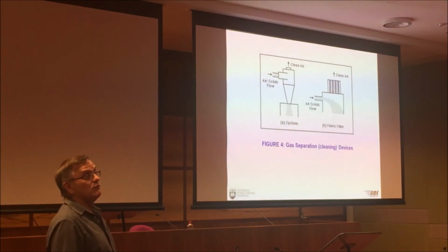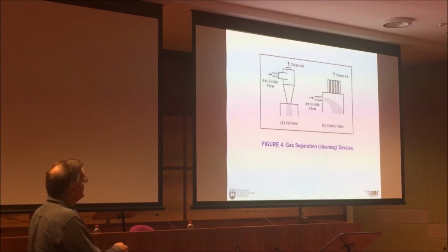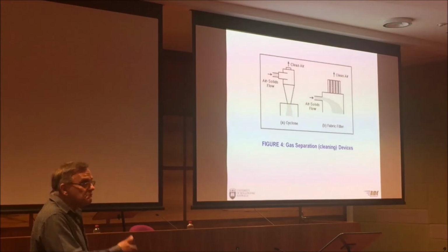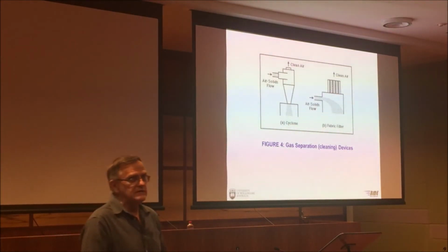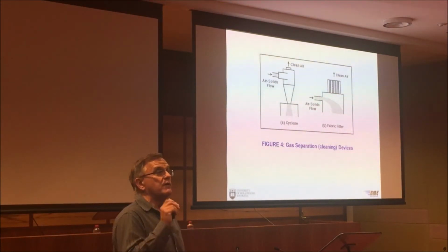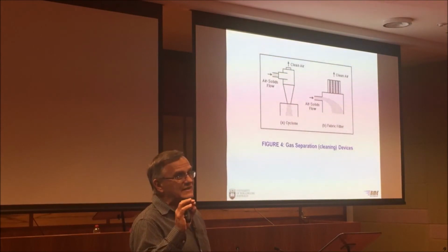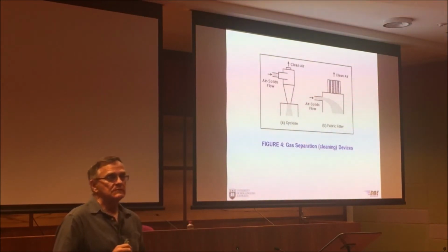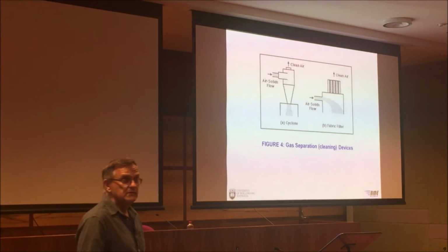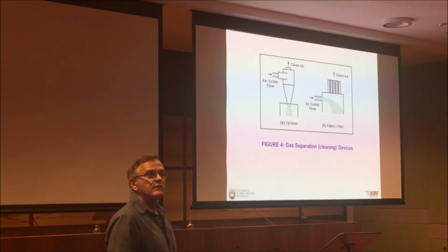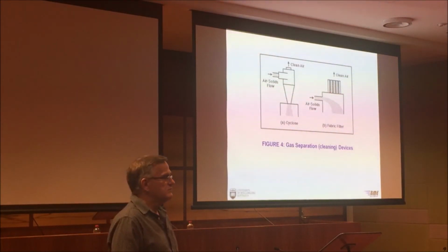And the other issue with filters, you have to be careful if you've got an explosible dust in here, you've got an electrostatic spark in there, you can generate an explosion very easily. So you have to buy even more expensive conductive filter bags. Right? So carbon impregnated bags that are earthed, so it doesn't generate electrostatic charge.